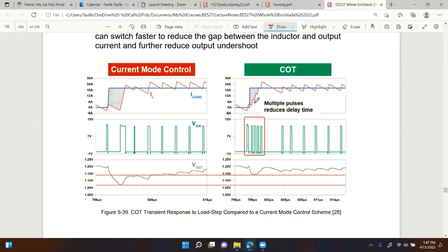Drops again, right? Because the pulse already expires. The pulse is already done. It drops again right there. That's why you see a drop. That corresponds to another drop in the output voltage and hits that threshold fast again and produces the pulse again. Produce the pulse again, right?